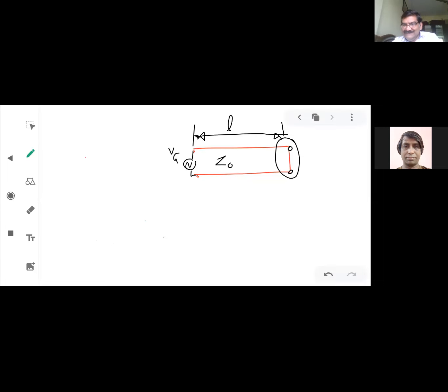So now there will be two kinds of power traveling on the transmission line. One which is coming from the generator side, and one which is coming from the load side. And these two powers will collide with each other. And if you look at the voltage quantity and current quantity, because these are the two quantities which are phasor in nature, they are vector quantities. So what is going to happen, we'll draw the graph here. So this is the dead end of the transmission line, right hand side. From here, if I draw the pattern of the two waves when they collide, which is called what? Standing wave. So it will be something like this.